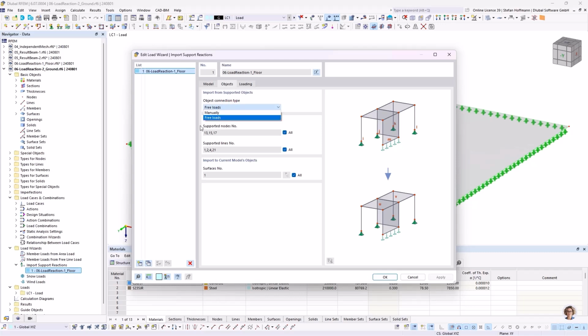So this now was added to the drop-down menu list, so that you do not have to assign the node numbers and the lines manually. Now you are most likely free and only bound to the geometry. And since it is now only geometrically projected into a certain direction, you should think about also defining the surfaces where you would like to import the forces.